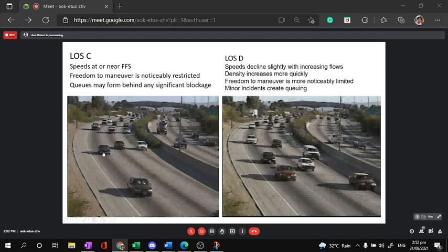a queue forms behind you, no? Nakapila, but the headway is long, so it's okay. It is safe to pass because the spacing and headway of your vehicles is large. And there's no blockage at all. This can overtake to the middle lane provided he watches this vehicle and so forth and so on.